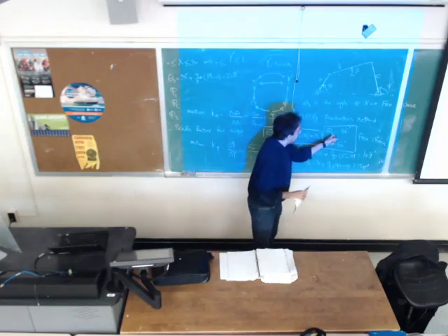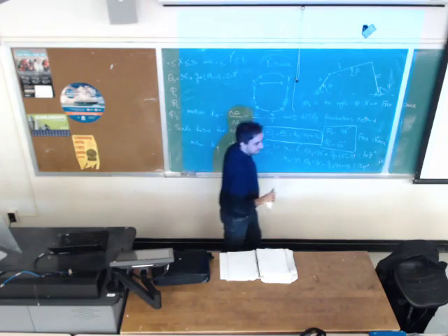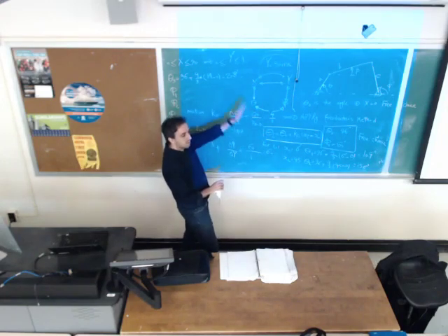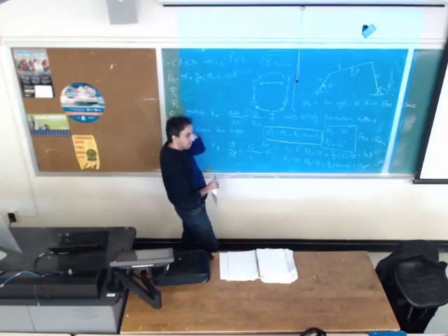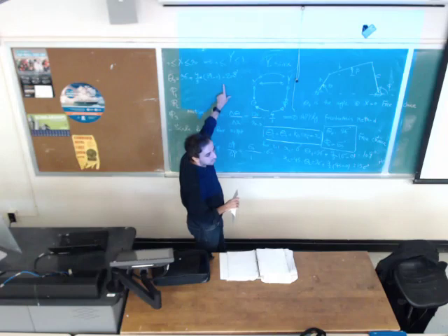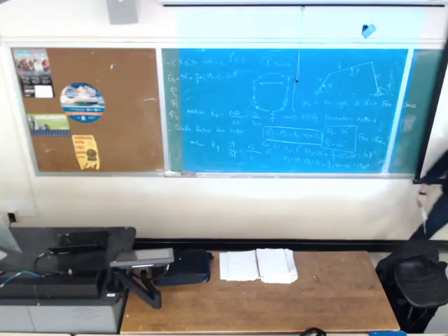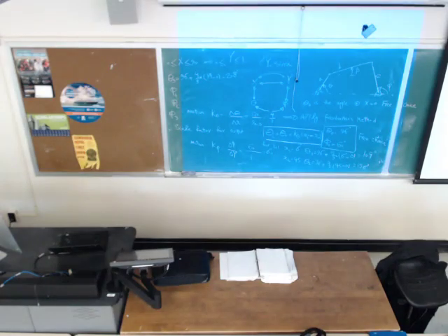So theta naught is 96. If I add it to 120, it's going to be 216. So it's going from 96 to 216, and I didn't pass that. Okay, so that means we must not pass 120. It's not the range, it's a delta theta. The range is 120, but at any angle that you start from, it should go only by 120 degrees. It's not the angle, it's the difference. It's how much you should move.